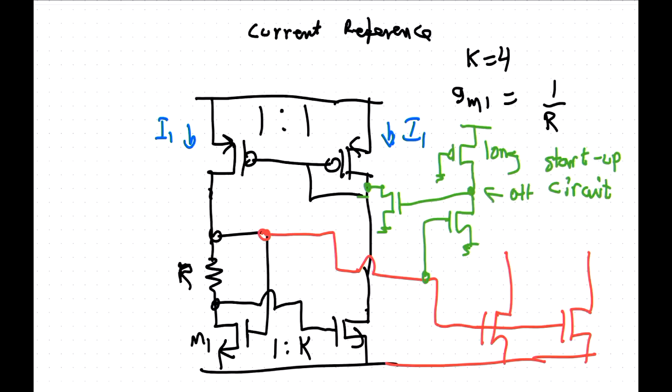But you can make a dynamic one. I haven't had the guts to do a dynamic one, but my students have more guts than I have, so I have seen it and it works fine. You can replace a pull-up with a capacitor essentially. Okay, all right, look, I think we've got to say that's it.